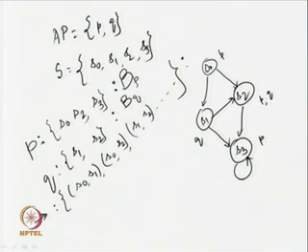And these are the state transitions that we have in our system, and we have already seen how to represent this transition behavior of the system with the help of ROBDDs. So, I can say that B arrow is the ROBDD representation of this transition relation. And you just think that if I am talking about ordered BDDs, all these BDDs have a computable variable order.